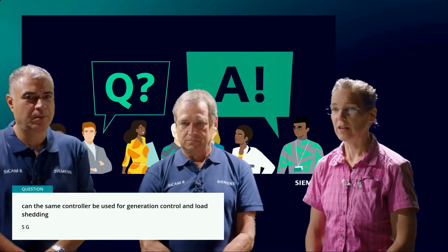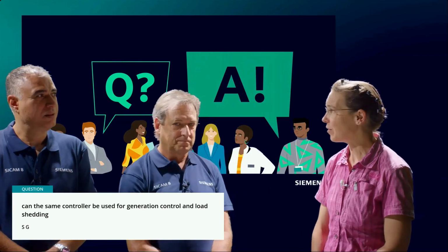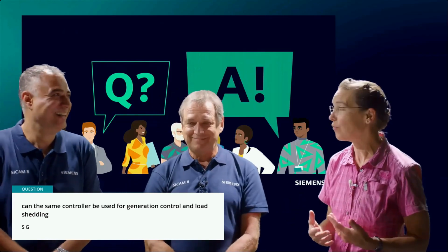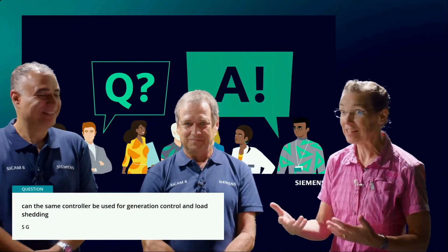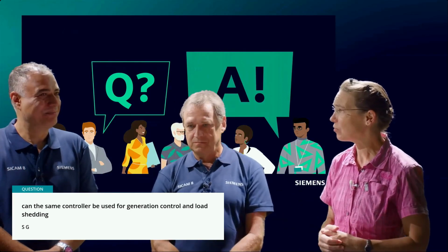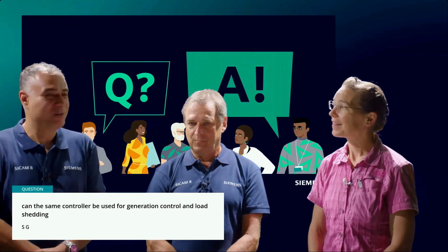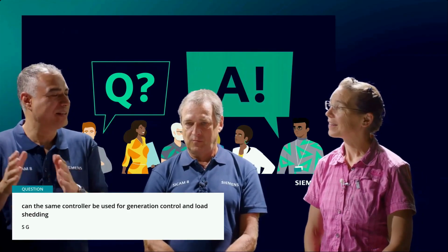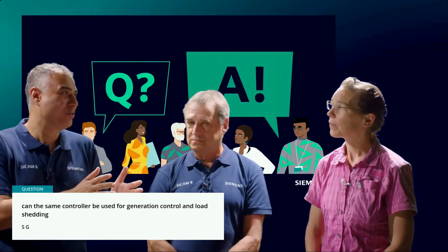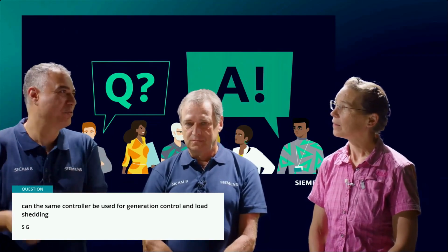Thank you. The next one is interesting. Can the same controller be used for generation control and load shedding? As we learned in the first part of the webinar, a lot of customers will start with asking for load shedding. Can they reuse the system and add generation control? For a small substation, yes, but for a big or large substation, we recommend one controller for load shedding and another controller for generation control, as we separate out the controllers.